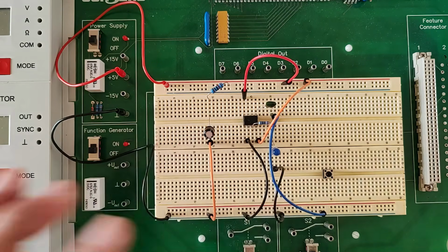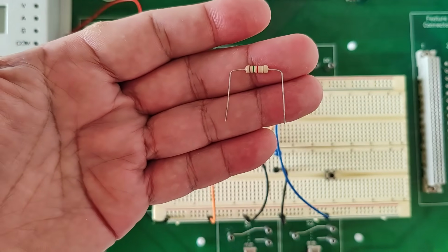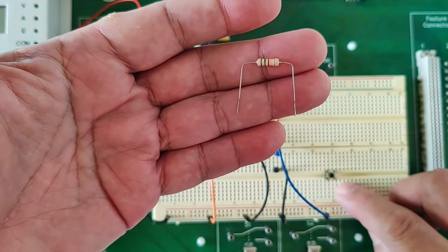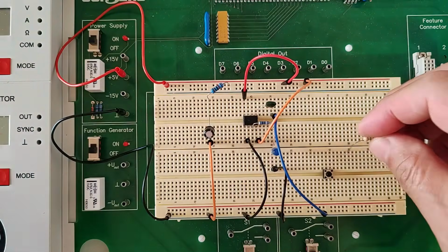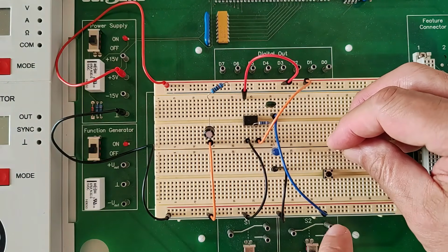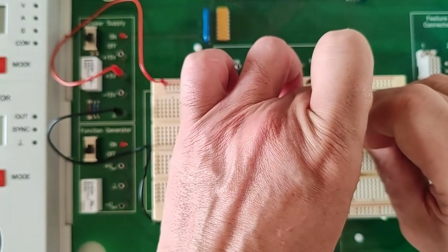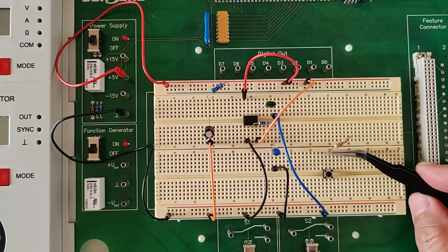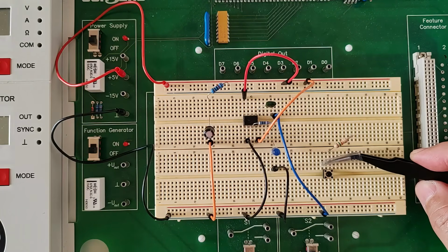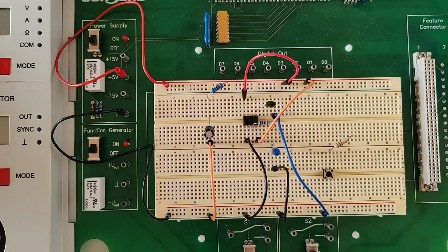So what I'll do is this. According to the circuit, I'm going to use a 1.5 kilo ohm resistor. I have it here. I'll connect it to one terminal of our push button switch. Okay, let me do that. Let me use the top leg there. Top leg here, top right. I'm going to connect my 1.5 kilo ohm here. Connect it somewhere here like that. Like there. So my 1.5 kilo ohm resistor here is connected to this upper left-hand leg of that tactile switch here. Now, the other leg, according to the schematic, will have to be connected to 5 volts.